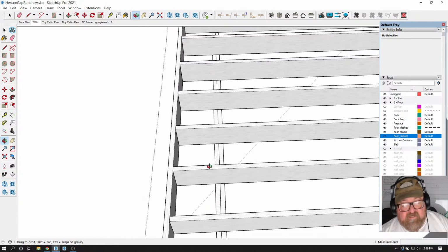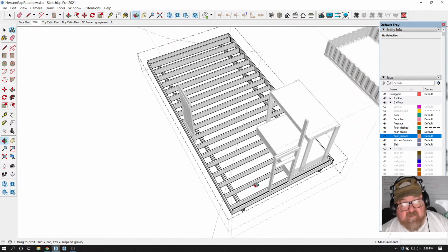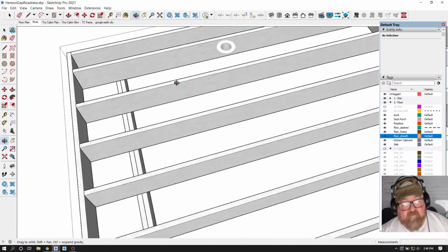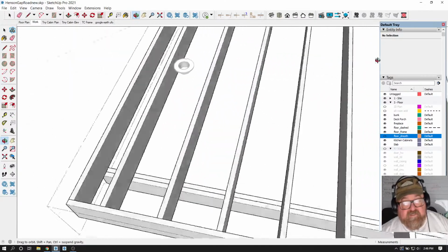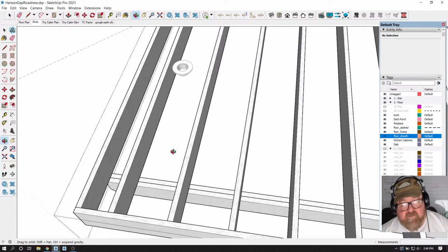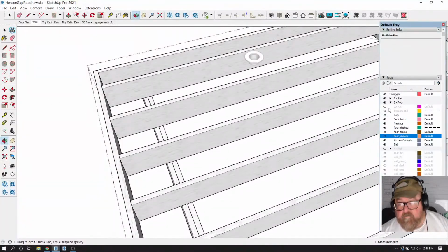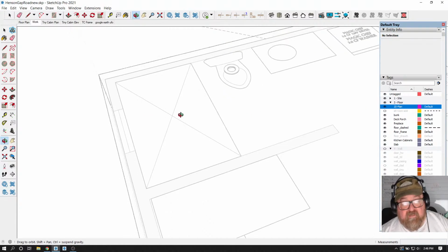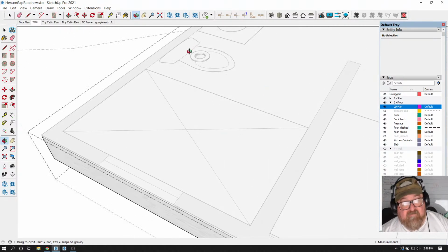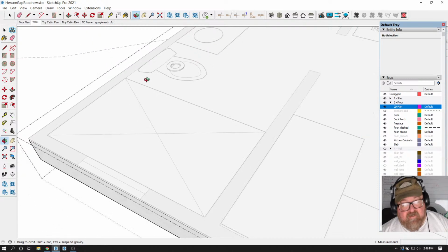I've got this all planned out. The toilet drain sits here, and I was going to address this floor framing. I've also got the shower. This is how I do my plumbing layout. I've got the toilet flange sitting there already, and I'll put a drain here for the shower. I'll just show you about where it's going to be. It's going to be about 3 inches off of this.